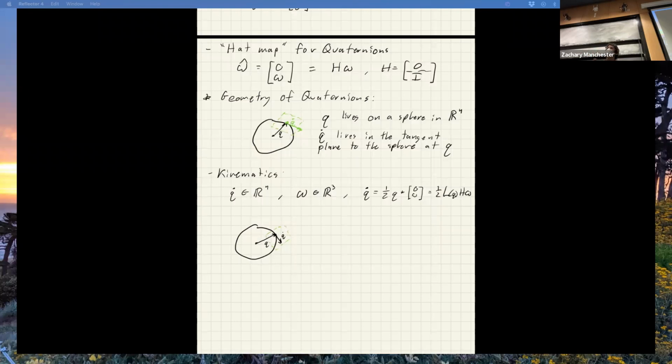It's written in the tangent plane at the identity. And then what this kinematics is doing is taking that tangent plane at the identity, think of it like the North Pole, if you like, and rotating it down to where the current Q is. So that's the idea. Let me write this. We'll do it like this. So here's omega, and it's living in this North Pole tangent plane.